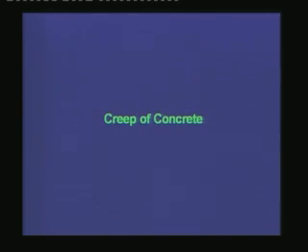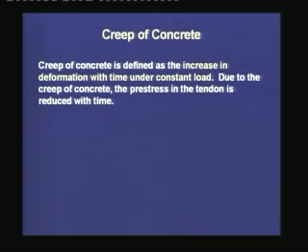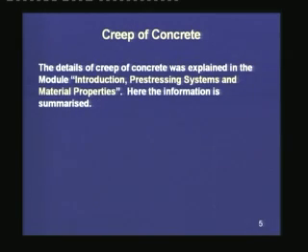First, the creep of concrete. The creep of concrete is defined as the increase in deformation with time under constant load. Due to the creep of concrete, the prestress in the tendon is reduced with time. The details of creep of concrete were explained in the module Introduction, Prestressing Systems and Material Properties. Here, the information is summarized.